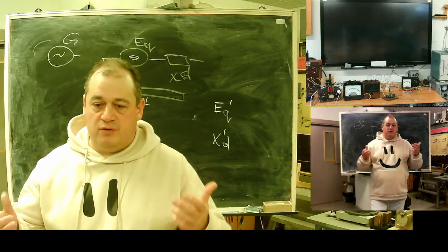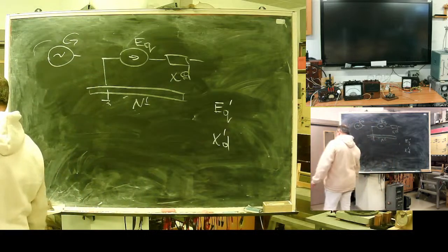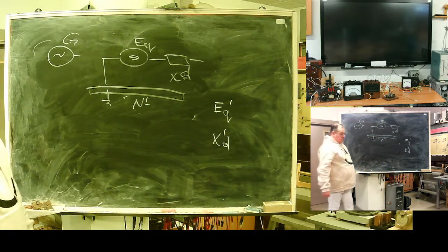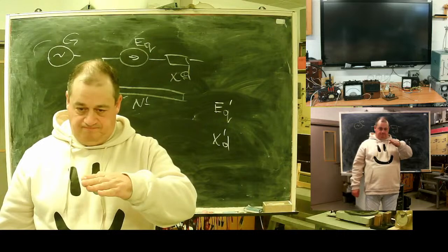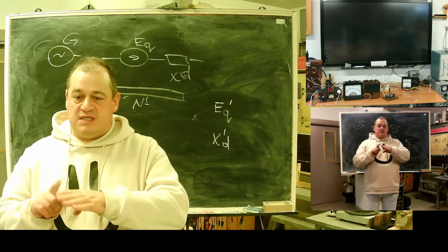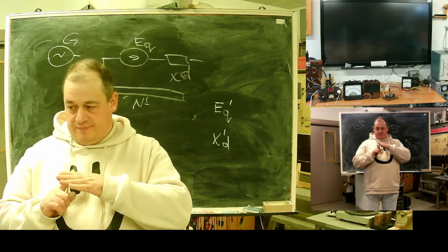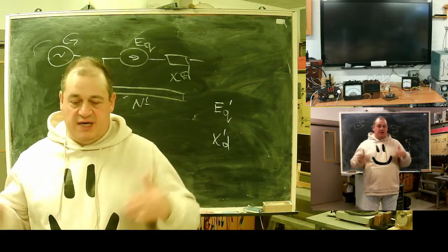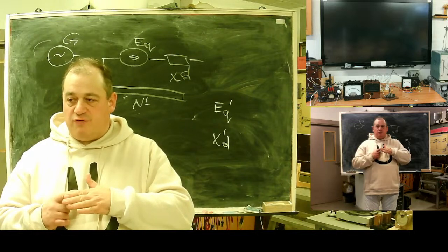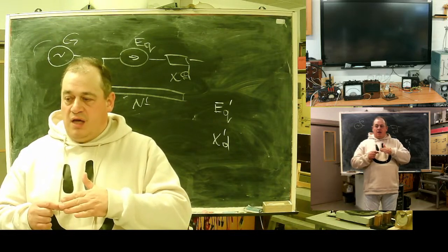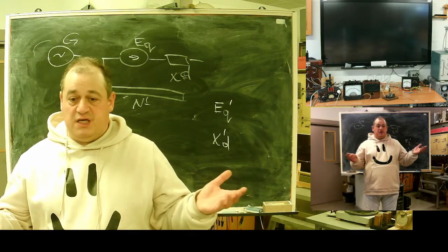Second, the turbine, this work wheel with propellers, can suffer from the so-called cavitation process. What does cavitation mean? When the vane goes through the water flow, on its trailing end a low pressure area is created. In this area of low pressure, water boils and becomes saturated with small bubbles of steam.